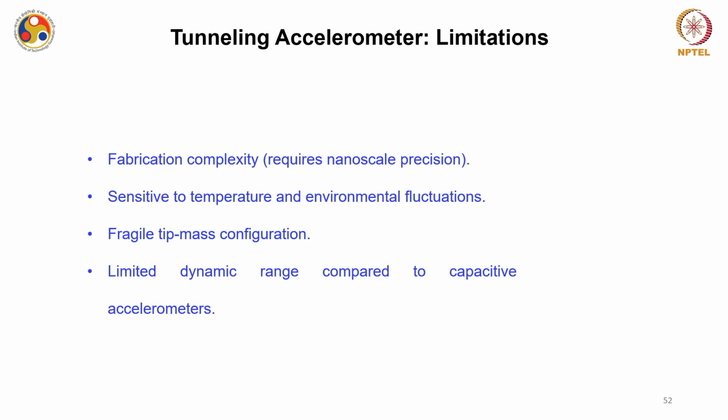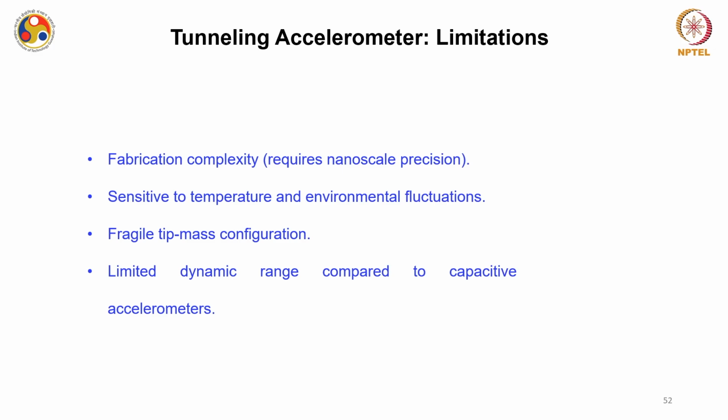However, they have various limitations also. The first limitation comes from the requirement of the clean room and the complexity associated with the fabrication of this kind of device. Then they are sensitive to temperature and environmental fluctuations, because you have seen that gaps of the order of 10 angstrom and below are involved. So they are susceptible to this kind of environmental fluctuation.